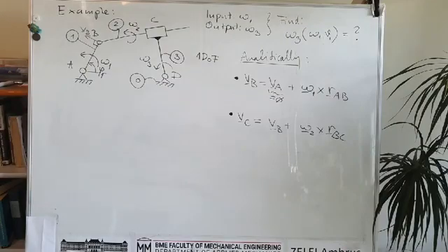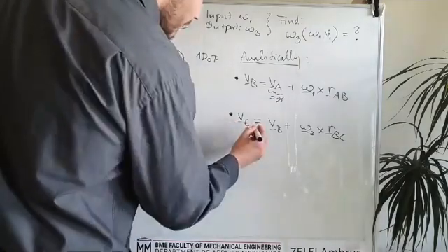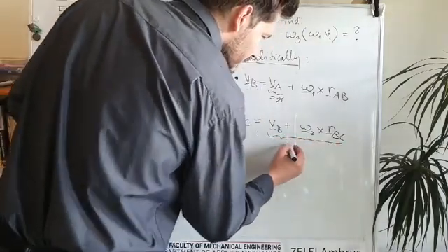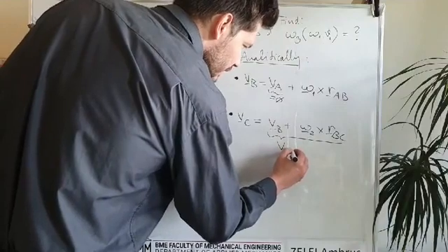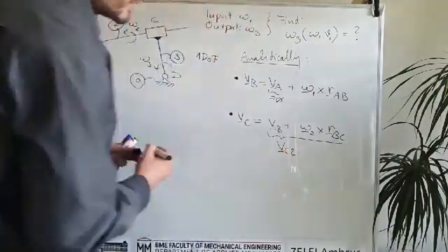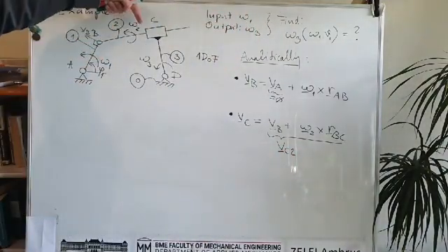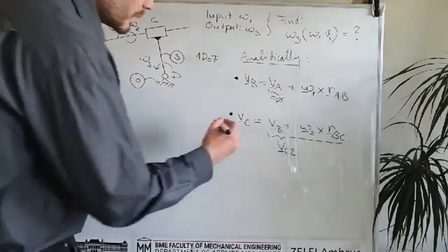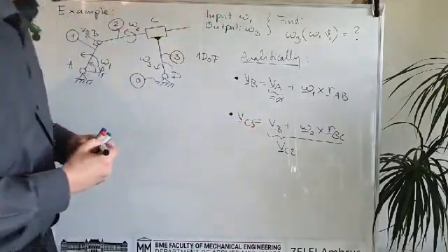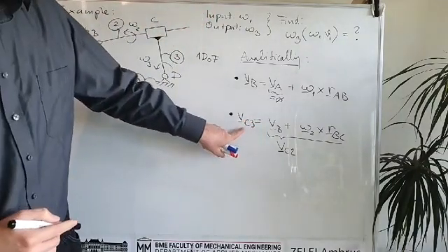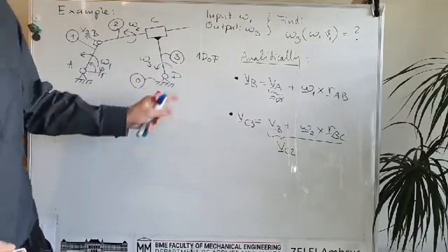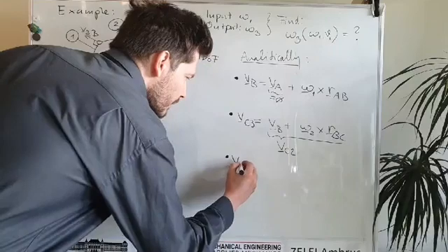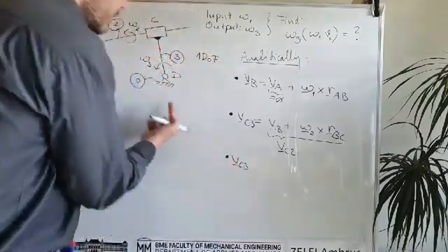So finally we have to extend this equation, because we say that this whole part here is the velocity of point C located in rigid body number 2, but we would like to calculate the velocity of point C located on rigid body 3, because we will have some other equation when we are coming from the opposite direction.